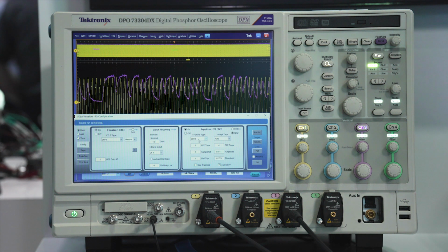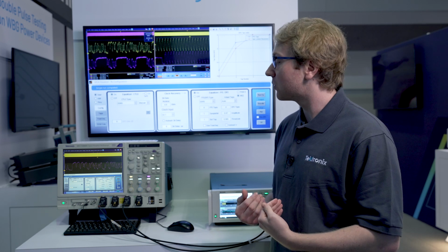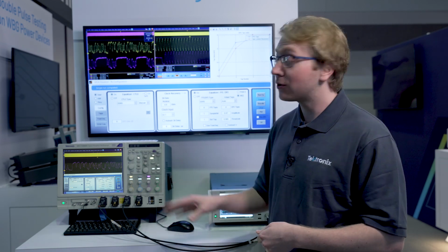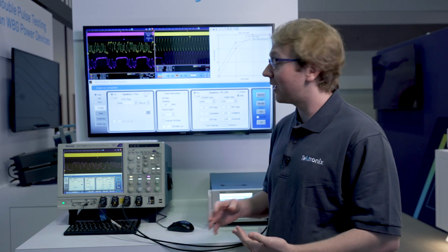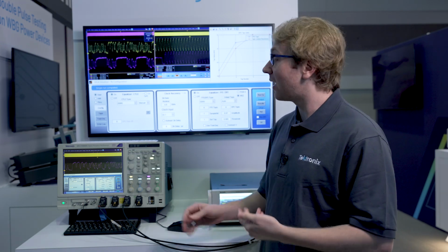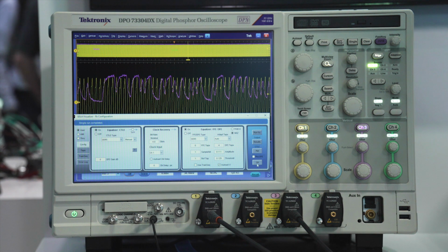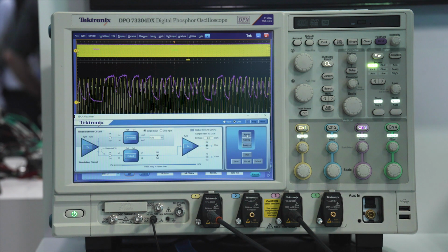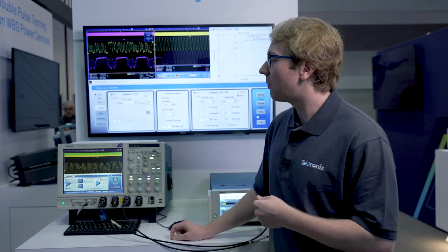Again, we have that very specific DDR5 module now for this software package, and I've set it up and configured it so after applying this stream of data, it's going to train these tap values. We'll see a small graph pop up just for a quick visual check to see if it all makes sense, and then we'll see a comparison of an eye diagram before and after the DFE equalization. So let's start that process by clicking apply, and we'll start seeing the scope do an acquisition, and then we'll see that graph pop up like I mentioned.